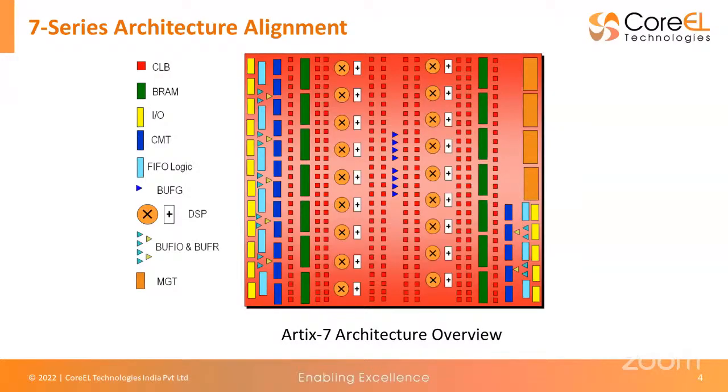So you can technically go ahead and design your own DSP, implement it using CLBs on an FPGA, and achieve your results. You can implement that and understand what is happening within your design, how it is performing. You can take out all those reports. We're going to look at all of this with a demonstration, but just for our understanding, this is possible, right?